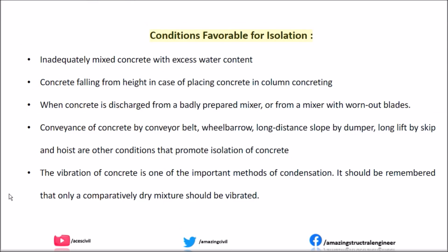Conditions favorable for segregation: inadequately mixed concrete with excess water content. Concrete falling from height, as in placing concrete in column concreting.